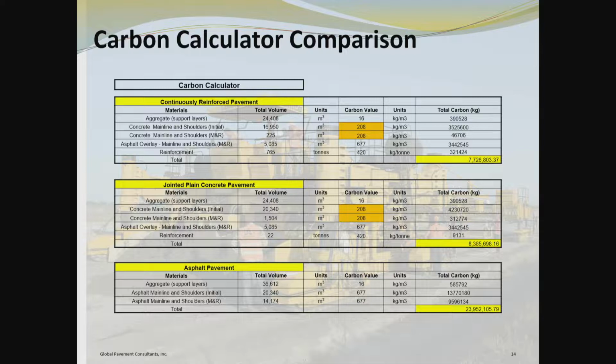So if you want to make a huge impact, don't do that. Diamond grind it. Diamond grind it, full depth repairs, partial depth repairs, joint resealing, whatever it happens to be, is going to be one heck of a lot less than that number. That's one of the options you can do. There are other things, but that is the most obvious thing.